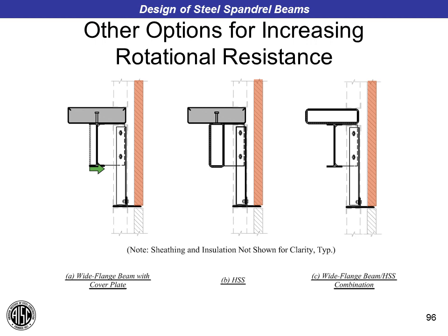And that you really only have to do over the length of the opening. An alternative to that is to use an HSS section, as you see here, in lieu of the wide flange, but be aware this may impact the connections at each end of the column and make those much more complicated, but it's certainly possible to do. Another solution might be to replace the slab altogether with a wide flange section, as you see here, to try to make this section more torsionally rigid. It's a little crazy to do it like this, but it has been done.